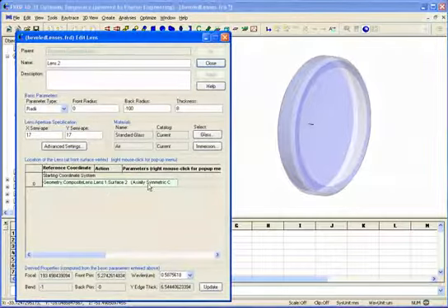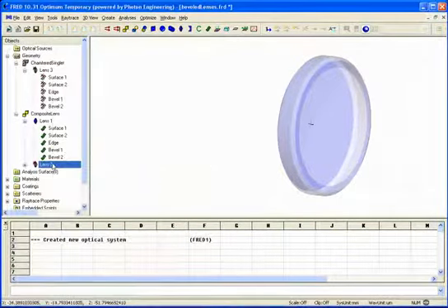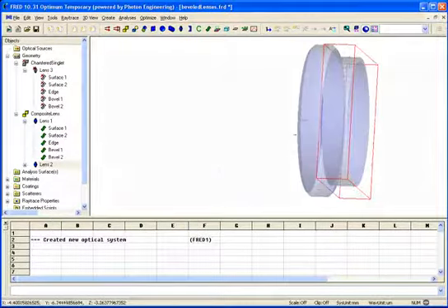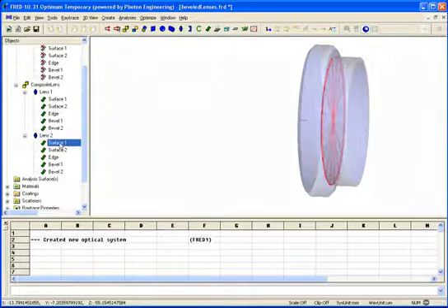So let's open it up again. Notice that I've set the starting coordinate system to be surface 2, which is the surface we just modified. So if I turn it on, now that lens element sits right inside that vacated aperture space. Now I need to expand out lens 2, and notice that I have this surface that still exists in the middle of the composite element here.